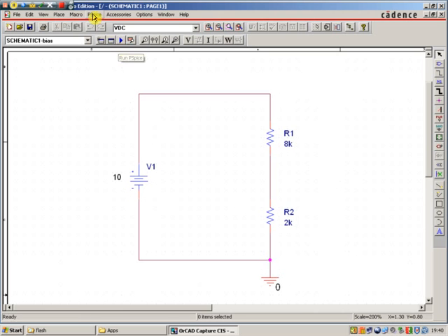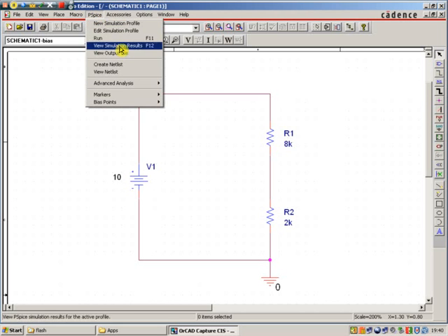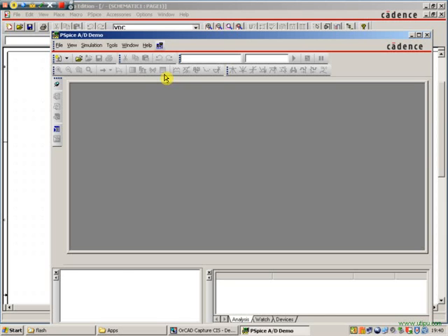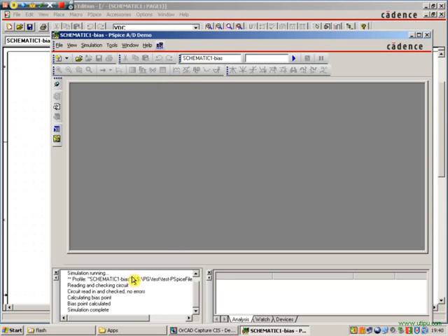If you know the quick keys, you can use an option, or you can go to the PSPICE menu and hit run. As you see there, the quick key was F11. So let's run the simulation. We now generate a quick netlist. We load all the variables that we require into the right table, and our simulator, a new window, has started.